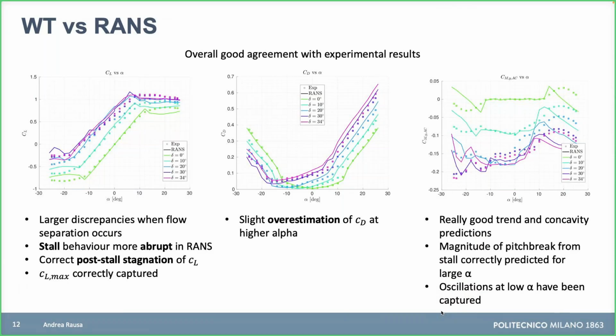So maybe if you run a simulation longer, then it will change the value a little bit. So it doesn't really change that much. What transition changes is how you reach stall. If everything is fully turbulent, then stall is delayed. Whereas if you have transition, then maybe you will stall faster.